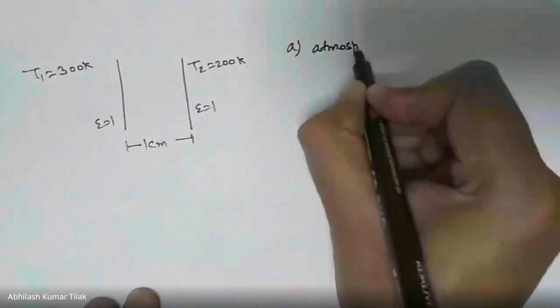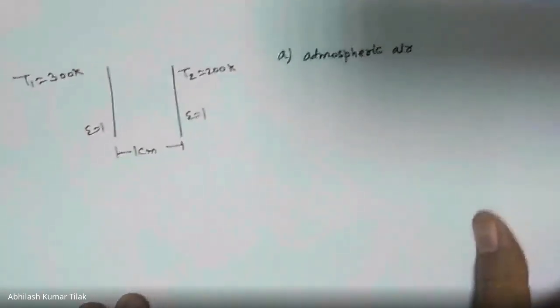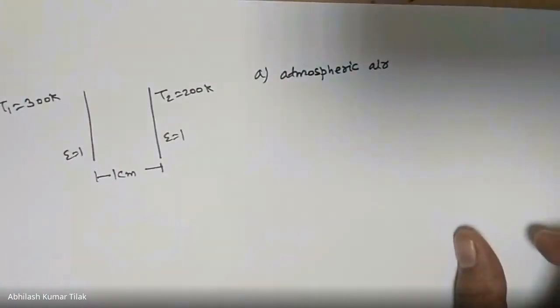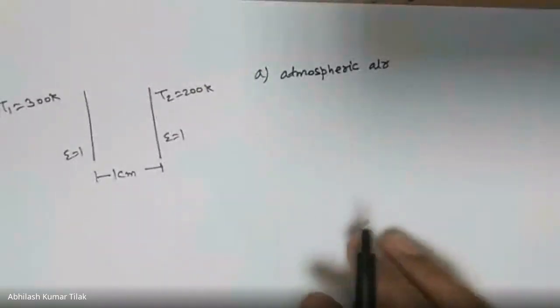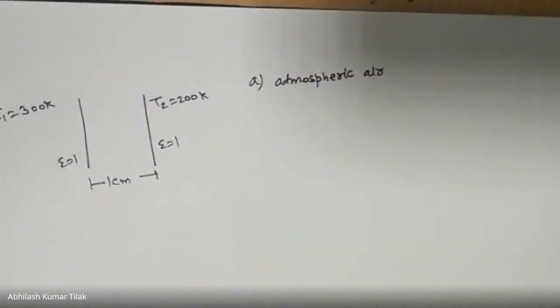The gap is filled with atmospheric air. So what modes of heat transfer will be here, if there is only air present? Convection and radiation. How can it be convection? Sir, if the air is stationary, we need to consider it as conduction.